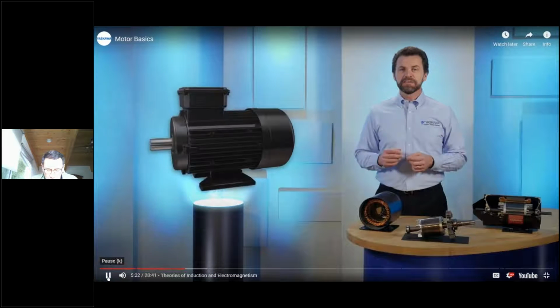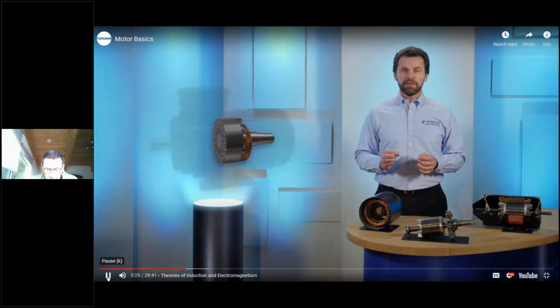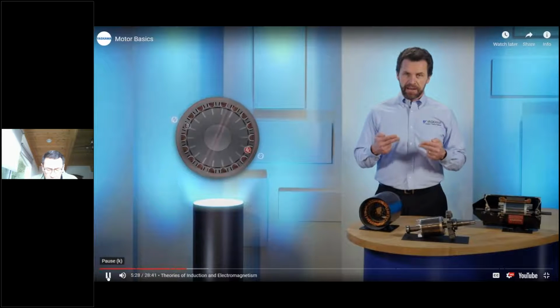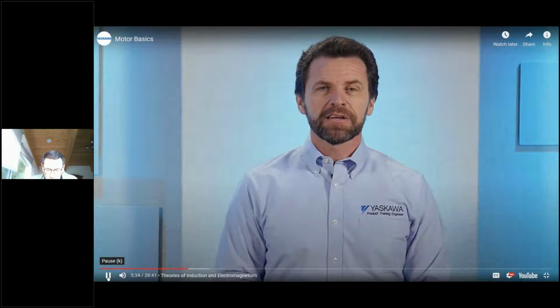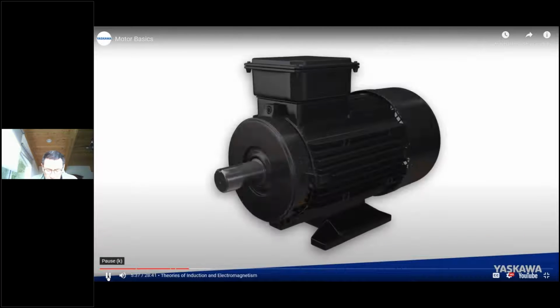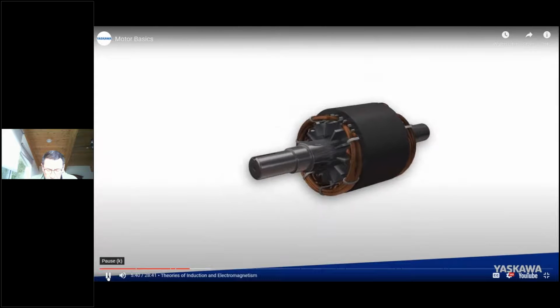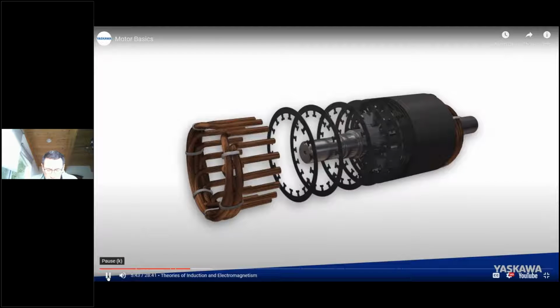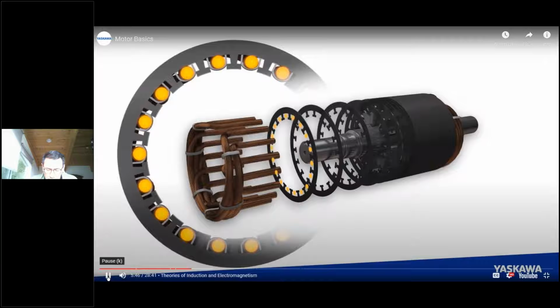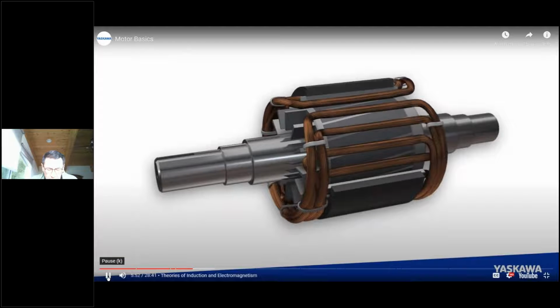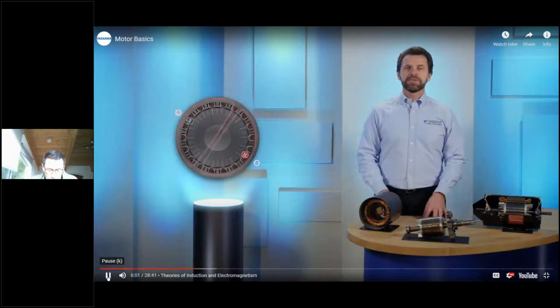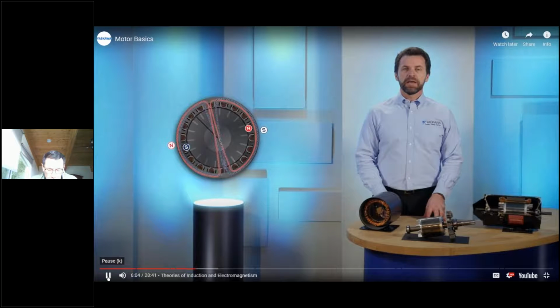In a three-phase induction motor, the stator produces the varying, or to be more exact, rotating magnetic field needed to initiate and maintain the induction process. And let's look at how that's accomplished. As we described earlier, the stator has a core of individual plates that are laminated together. These plates have slots in them, which allow insulated electrical windings to pass through the core. The stator windings are distributed around the stator in such a way that when current flows through them, the stator produces a magnetic field.